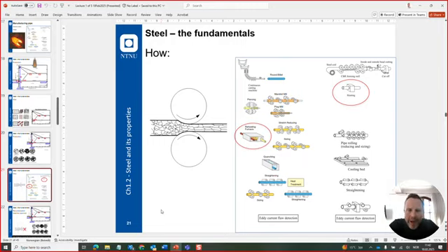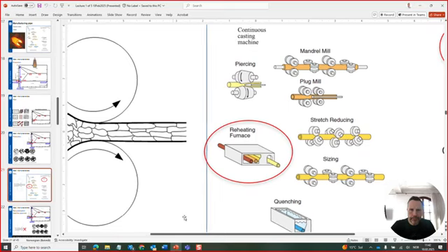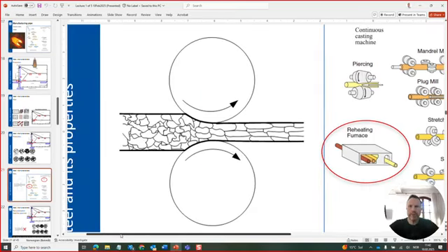This drawing, and I will zoom in so that you see the milling better, changes the grains from being nice small grains at random size and cohesion to elongated grains. And you can also think that the atomic lattice inside each grain is quite stressed by this. There is a lot of tension put into the lattices.